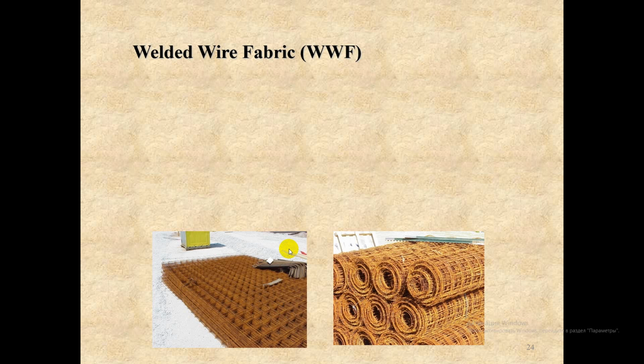Steel fabric for reinforcement of concrete is covered by building standard 4483, which gives 4 basic preferred types: A for square mesh floor slabs, B for rectangular structural mesh, also for slabs, C for long mesh for roads and pavements, and D a small diameter wrapping mesh for binding concrete fireproofing.